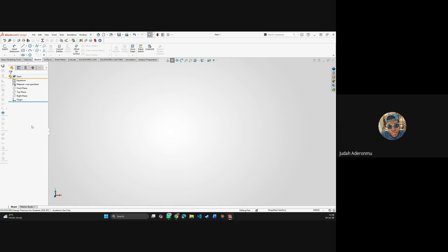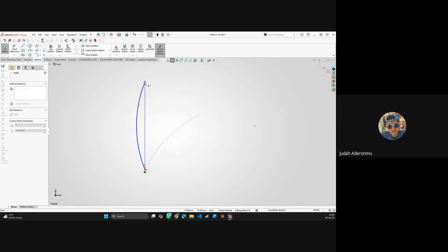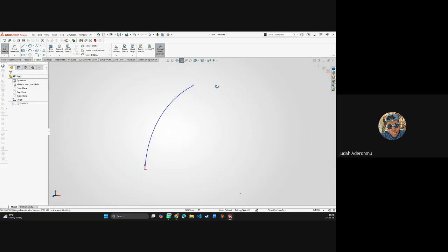Okay, new sketch. Let me select my front plane. I'm going to just select a 3 point arc. Just draw an arc here. One arc is enough. Just bend this to get what I want. Okay, great.